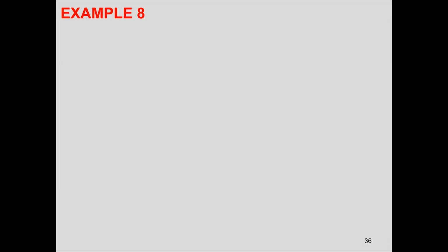Yes, unless the system is moving with regards to elevation or with regards to velocity. If there is no information given about the system moving with regards to some reference point in terms of elevation or in terms of velocity, you will assume your system to be stationary if it's a closed system.